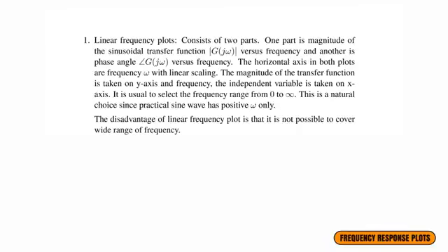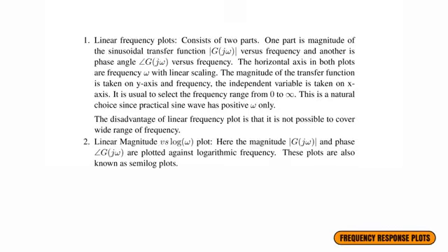One is called the linear frequency plot. In that, the x-axis frequency is taken in linear scale, and the y-axis magnitude is taken either in linear scale or in decibel scale, whatever it may be. Then there is the linear magnitude versus logarithmic frequency plot. Magnitude is taken in linear scale, but frequency is taken in logarithmic scale.